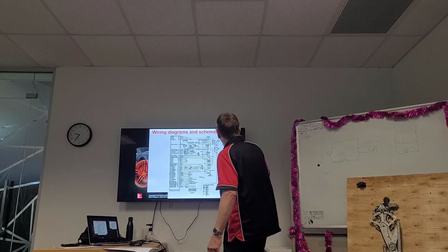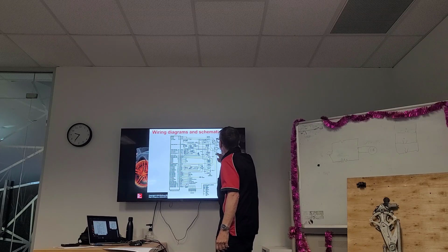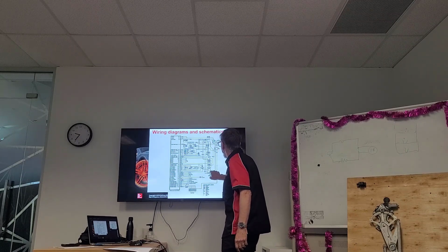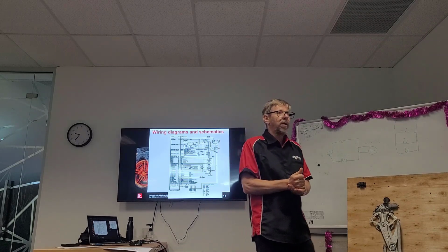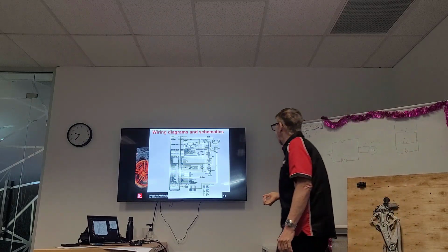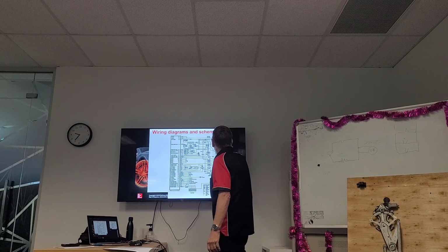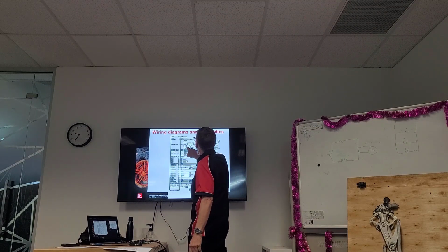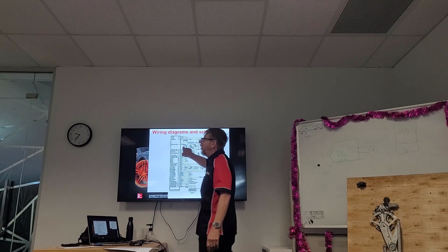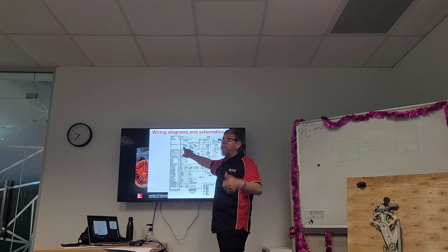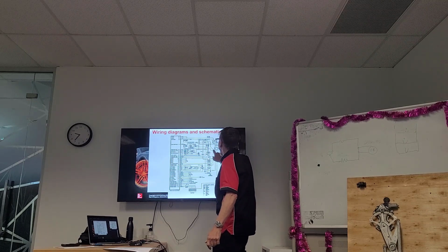If we have a look at this, if we follow this down, look at the dot here. We're joined to what? And what's that symbol down there called? Ground. A ground. You see how we can tell that's a ground? Also, if we come back and follow this all the way to this other relay, which is a fuel pump relay, is that a power? Ground. Because why? It's joined to the same ground.